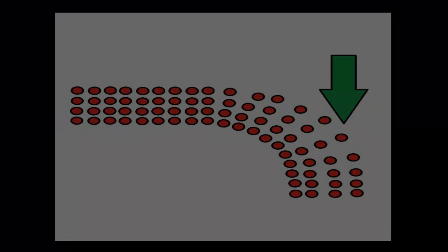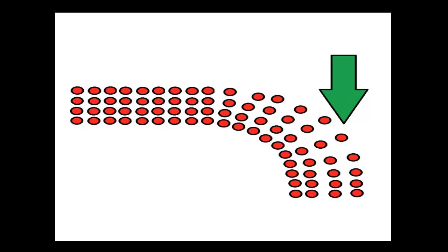Elastic deformation is a non-permanent deformation. This means the material will deform under an applied load. However, when the load is removed, the material will return to its original shape. In elastic deformation under loading, the bonds between the individual atoms in the lattice are stretched, allowing the material to deform. When the force is removed, the bonds and also the material return to the original shape.